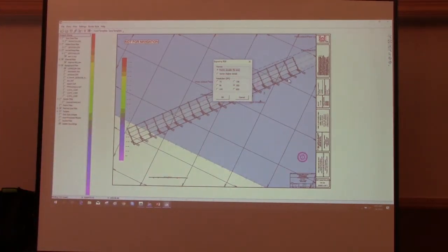Can I ask you a question with regard to that right there? If you export to PDF, what I found is that if the density of your soundings is so tight, like a 3x3 grid of your soundings, and you hit the option to not display the soundings where they overlap in the plot, it'll plot it and you can see it, but when you go to the PDF, it gets rid of that and it just looks like you threw 10 million points. It doesn't maintain the overlap.